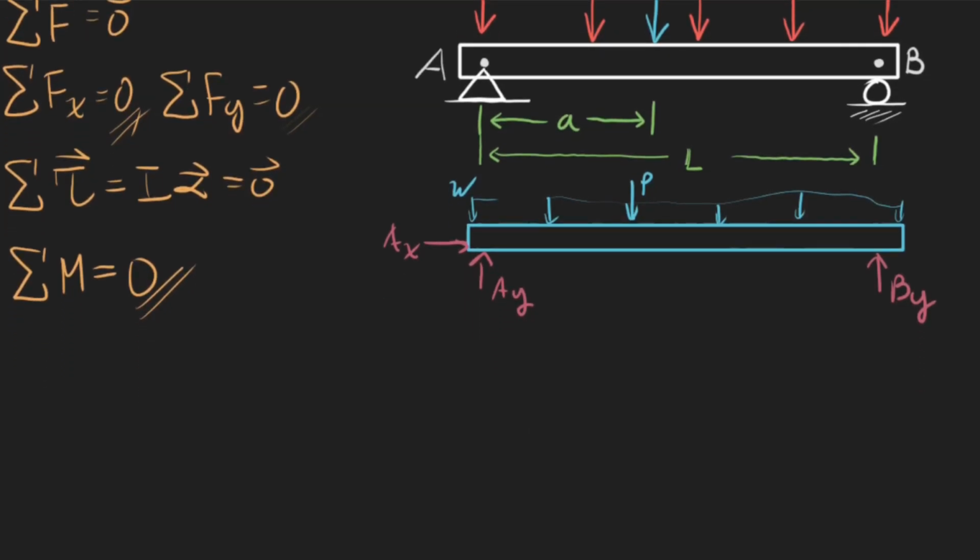So basically the idea here is that the area of this entire load with the applied distributed load can be simplified to just a single force at the centroid. So the centroid is kind of like the center of mass if you assume that the density is evenly distributed. So if you imagine I just have like a simple square here, the centroid is going to be right in the middle right here, right? And so what I can say is that if this is an entire like area of a load right here, I can replace it with one force right in the middle.